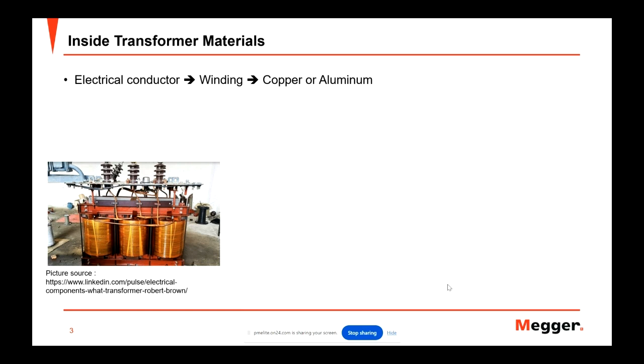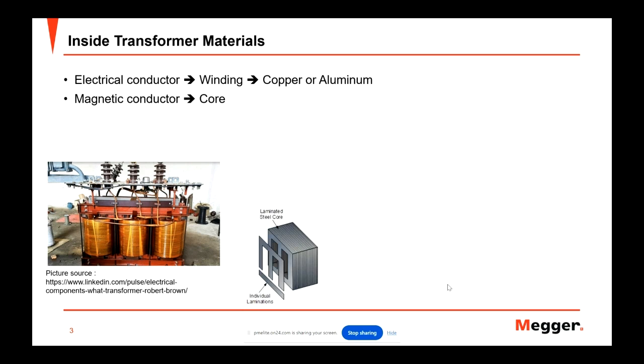If there is some obstruction, such as an untightened bolt or bad connection, it will cause high temperature inside of your transformer. Next is the core. It is the path for letting the flux flow. It also can create heat through the losses, such as eddy current losses or hysteresis losses, or the magnetic losses, all of which can create heat and affect the system inside your transformer.